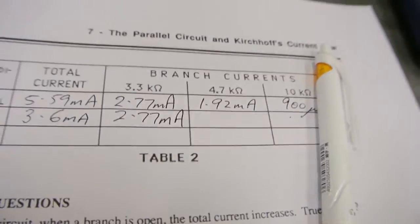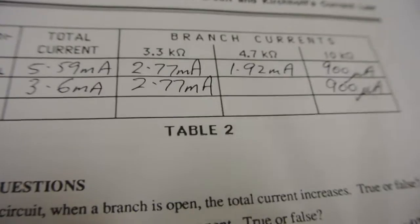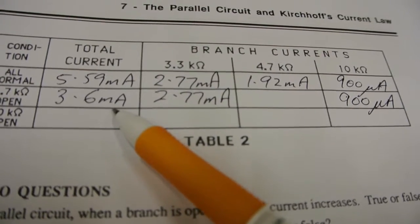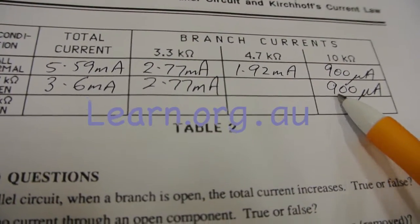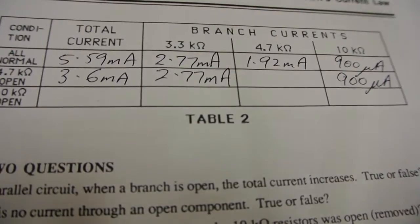I go ahead and I record that in table 2. It starts to become quite clear that although the total circuit current has changed, the individual branch currents for the resistors that were not open circuit remain the same. I'll go ahead and I'll do the last row in table 2.